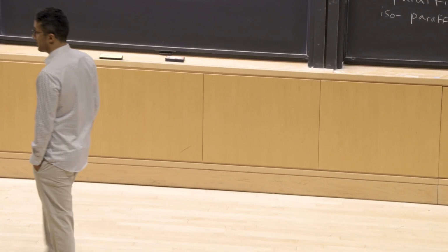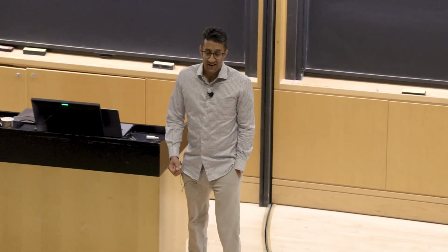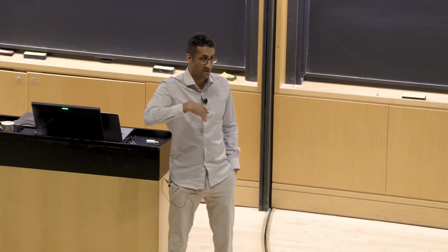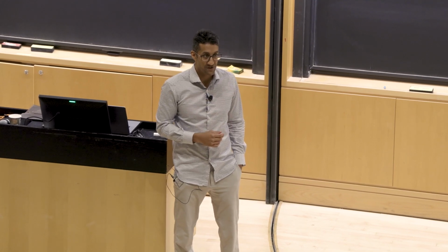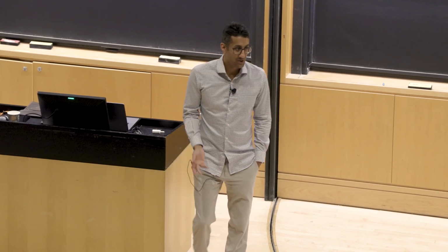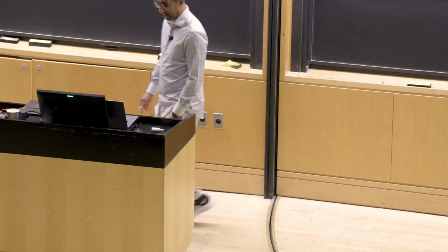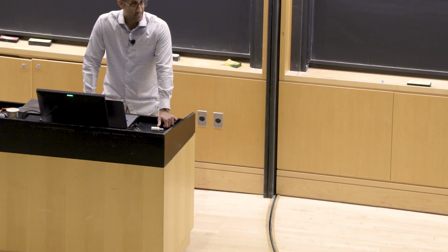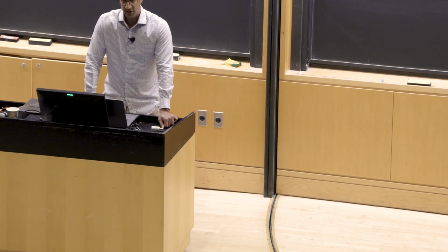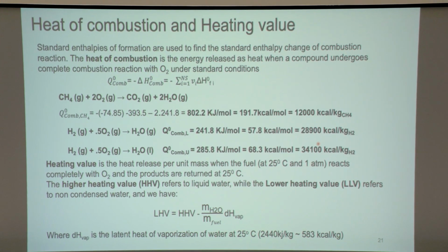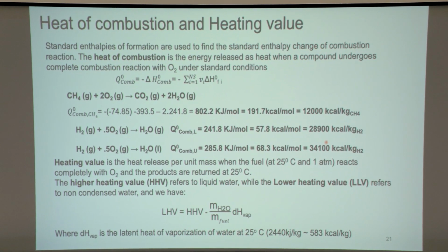So typically, different engineers in different industries will come to us, you're working in automotive engines, why are you talking about the lower heating value? You should use a higher heating value. Well, it depends on the system. Most of the time, if you're working in aircraft and transportation and engines, we use a lower heating value. If you're working in power plants with combined cycles or steam cycles, we'll use the higher heating value.